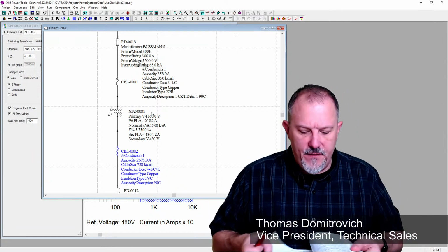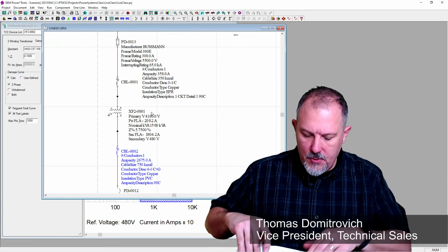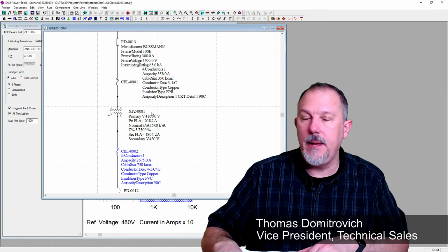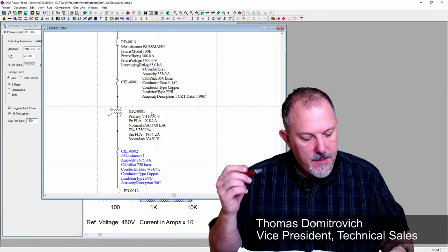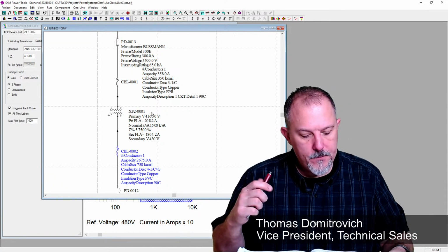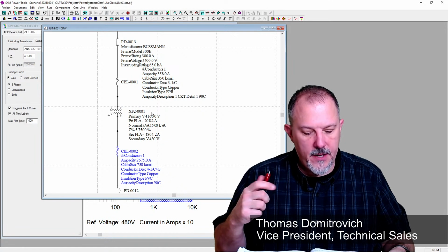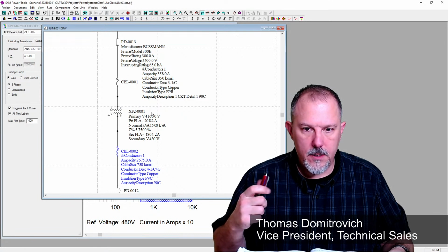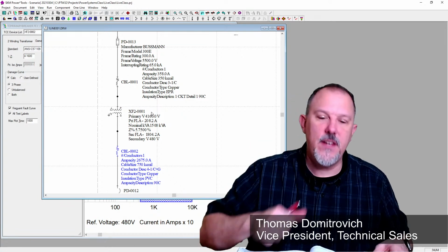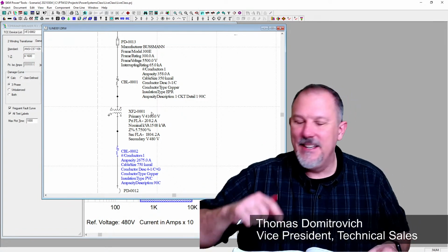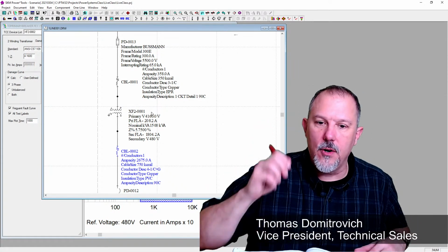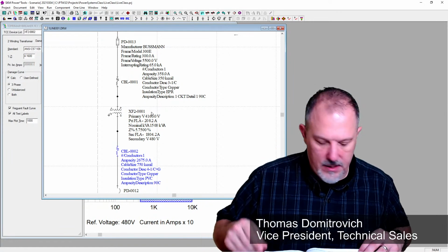So I'm using table 450.3a and not 450.3b, because B is for transformers 1,000 volts and less. Yep, 5 750s. I thought that was right too, but good. Thanks for checking that for me, Ryan. So we are good for 5 750s.